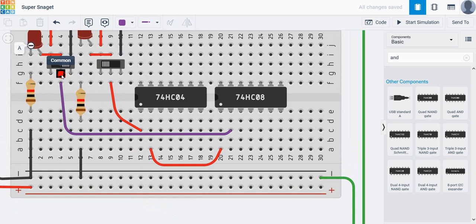And so now I have my signal A connecting to the one input of the AND gate that's over here. I have my signal B inverting over here, connecting then from this output to the other input of the AND gate. And now this one over here is going to be the output which implements the function A and B not.